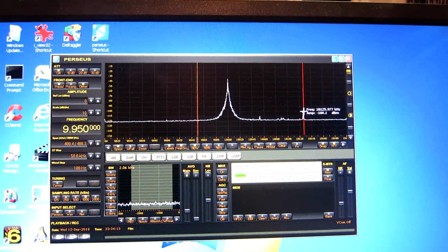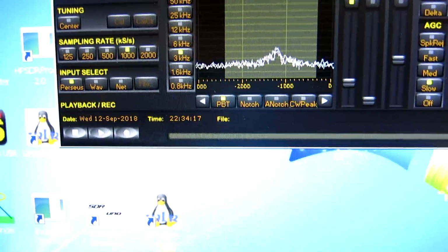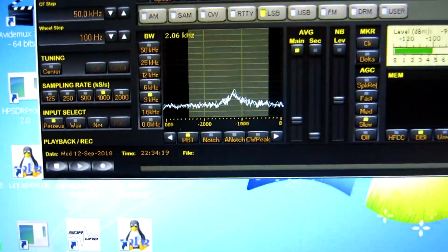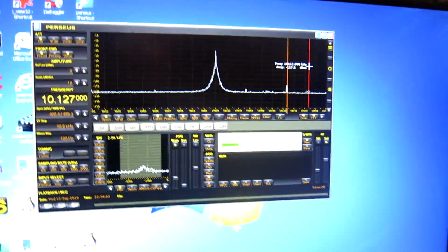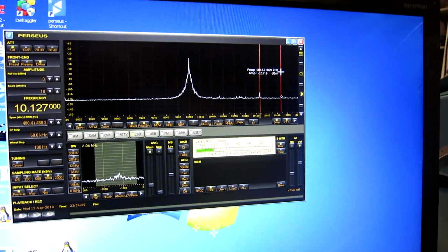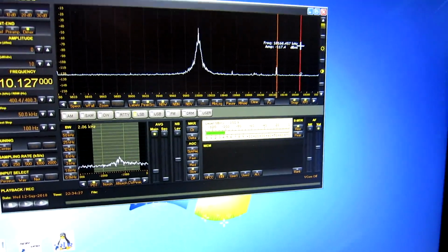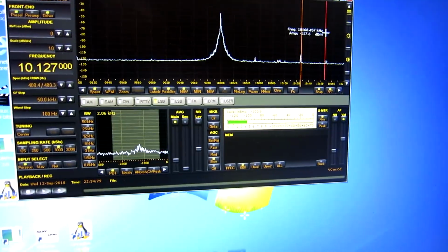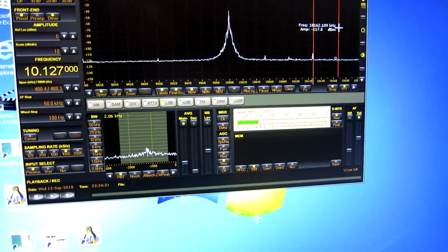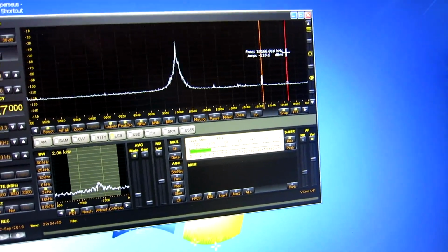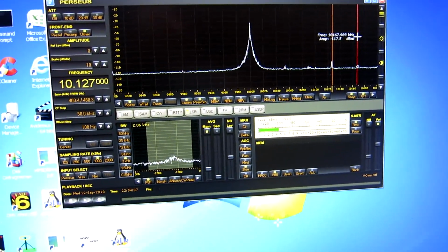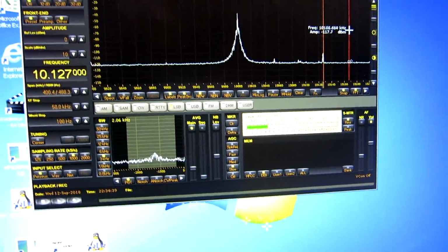If I click on one of them, you can see it's not a sine wave, it is a noise hump. This is something that I previously attributed to parametric oscillations in ferrites or capacitance diodes or whatever. But it happens also with this setup where there are no such components.